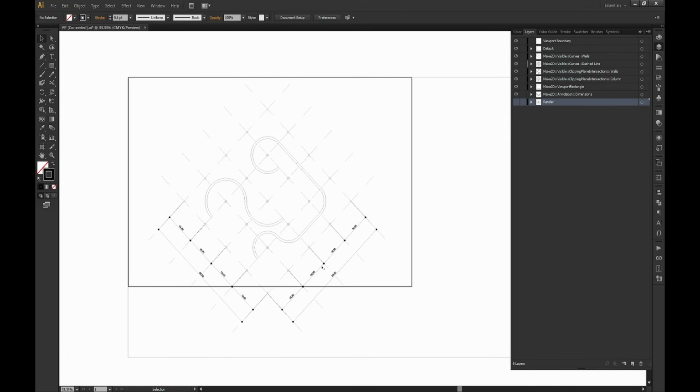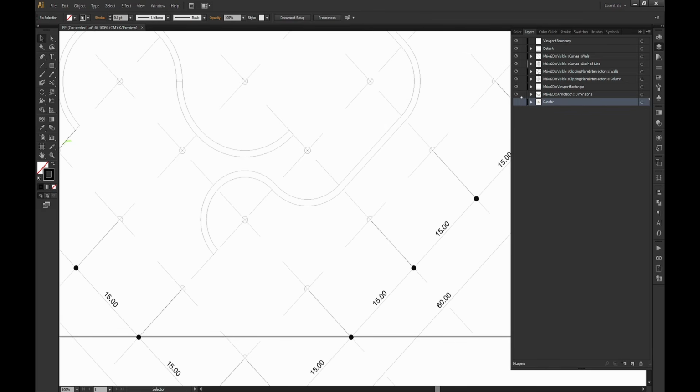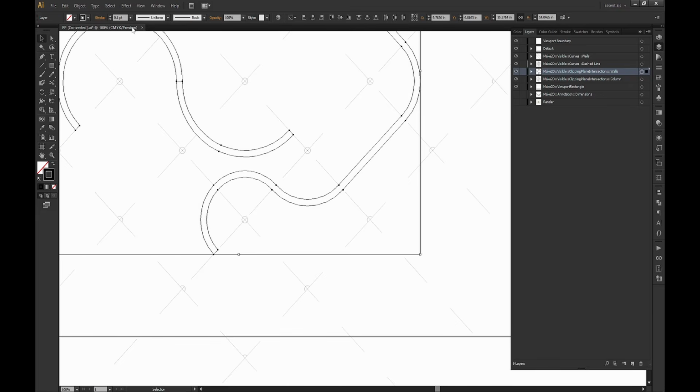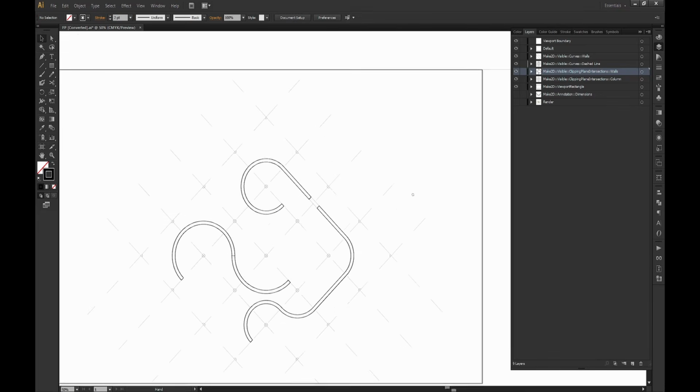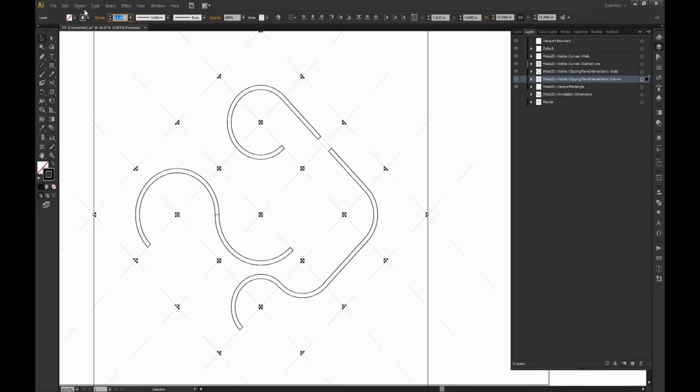And I'm just going to thicken up these lines, right? So for example, let me actually turn off my dimensions as well. And let's do my clipping plane, the walls, right? Like these right here are going to be thick. I can select these. Let me give it a thickness of 2, just a nice thickness, so it pops a little bit more. Same thing with the columns. I can give the columns a thickness. Select all the columns. I'll give a thickness of 2.